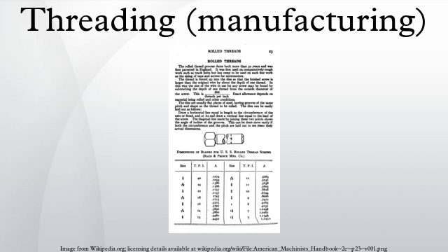The cutting tool tip is shaped like a drill or center cutting end mill, while the body has a thread-shaped form with a countersink cutter form near the shank. The cutter first plunges to drill a hole. Then the thread is circularly interpolated just like the multiple form cutter described above. This tool drills, chamfers, and threads a hole all in one compact cycle. The advantage is this process eliminates a tool holder, and tool change. The disadvantage is that the process is limited to hole depth no greater than 3 times the diameter of the tool.